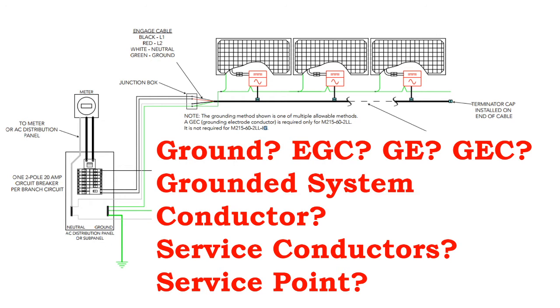Now there's another path to ground that's not the final grounding electrode conductor to the ground rod. The other one's called the equipment ground conductor, and that's what connects all pieces of metal on a home, on an electrical system, to the grounding system. And so it's a pathway for metal bits, the module frames themselves. If they start carrying current from the solar array, they're grounded, and that electricity should, rather than remaining up on the rooftop as a faulty open circuit voltage that, if you touch it, could electrocute you, instead be shuttled down to ground.